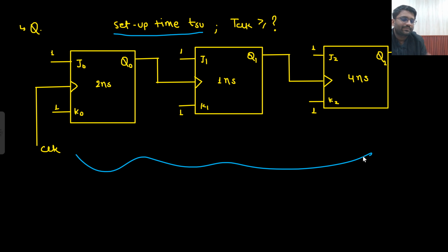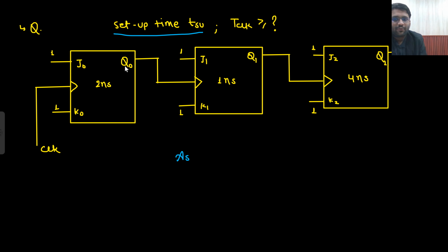What kind of circuitry is it? It is your asynchronous down counter. Is it synchronous? No. Why is that so? Because the clock is being fed from the previous output. So it is asynchronous. Is it an up counter or a down counter? It is a down counter. So it is an asynchronous down counter. How do you remember? Positive, positive will repel each other, that means goes down. Or if it was negative, negative, then also goes down. If negative, positive, goes up.